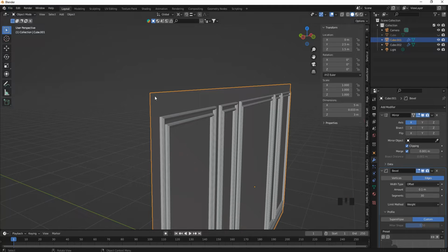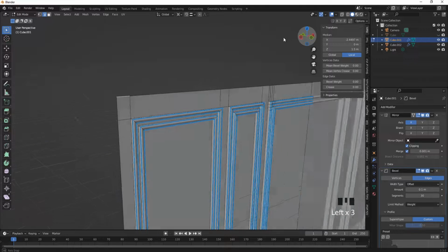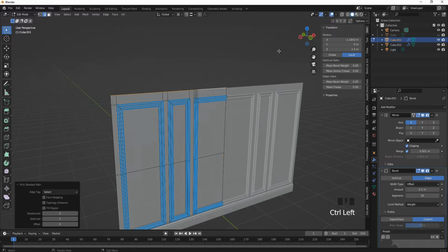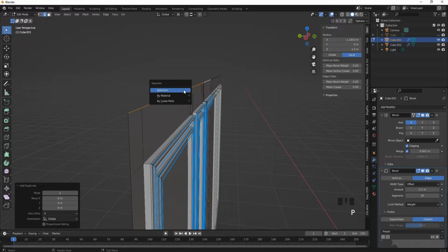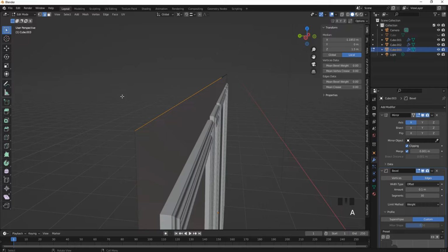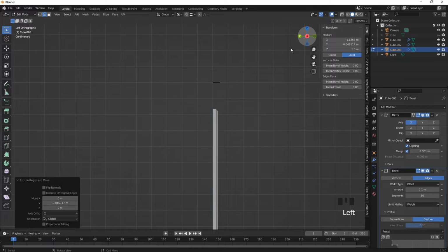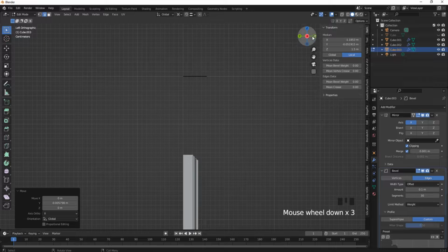and then let me tab to get inside of the edit mode, and then I'm going to select this edge, control click the last one, and I'm going to press shift D to duplicate it, and then press P and then selection. Now we have this. Then I'm going to tab again, press A, and then extrude it in the Y axis, press E and then Y, and extrude it somewhere around here. I think somewhere around here we could maybe G Y, move it like this just a little bit.